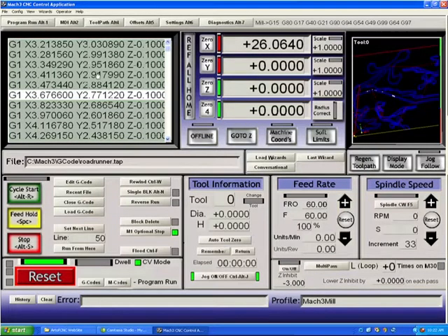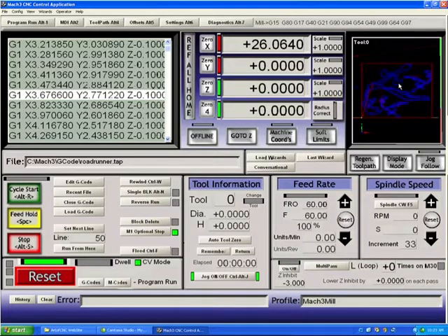Clicking once again will take you out of focus for that window. The Toolpath window itself, double-clicking will reset it to a plane and reset it to a size. The red box going around our Toolpath is simply the extrema of the file. The program is telling you this is the highest Y value you have, the lowest Y value, the minimum X, and the maximum X values.